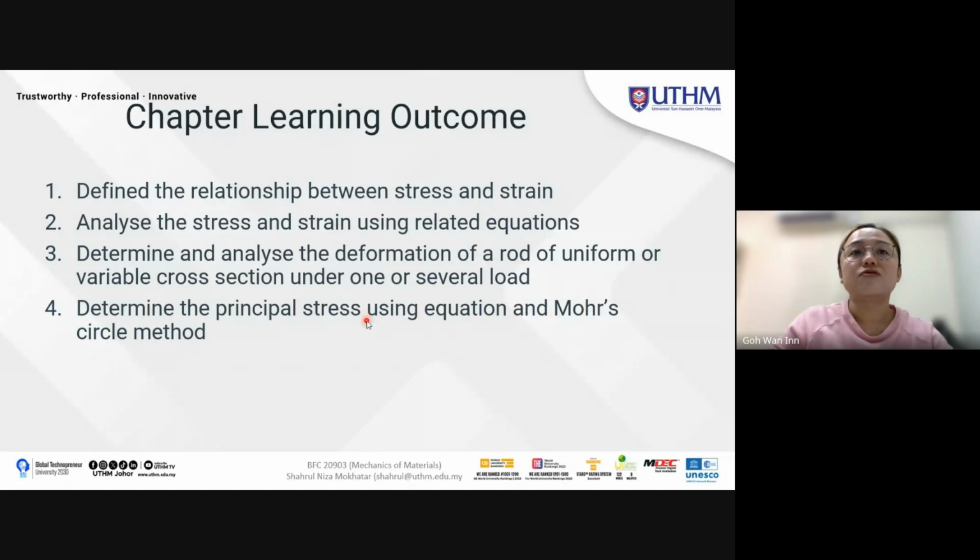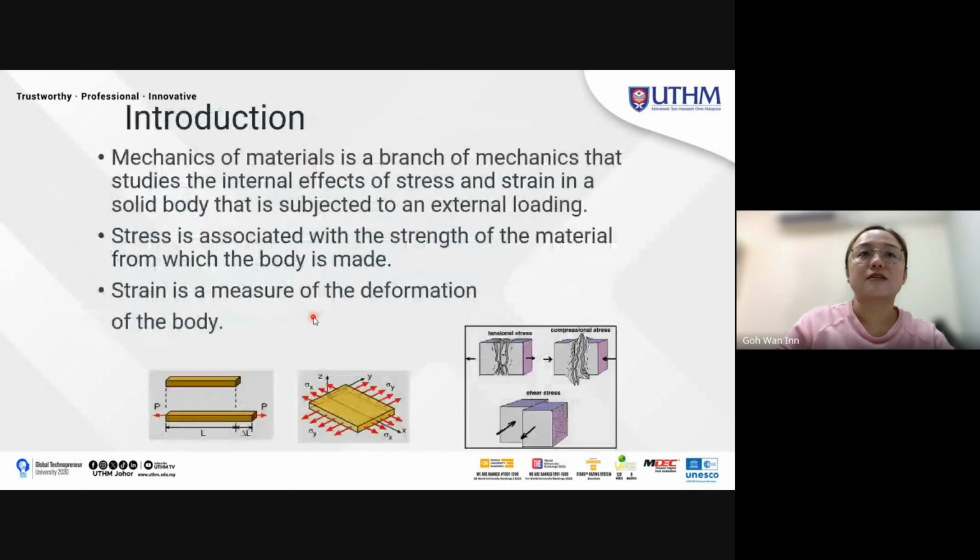This one includes chapter 2 already. Mechanics of materials is a branch of mechanics that studies the internal effects of stress and strain in a solid body that is subjected to an external loading. The load is from outside. Stress is associated with the strength of the material the body is made from. Strain is the measurement of the deformations, either becoming longer, elongation, or shorter.